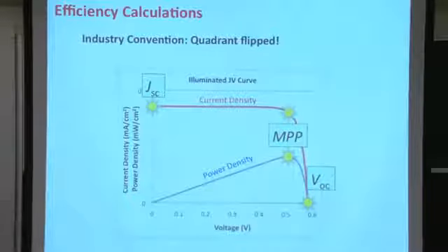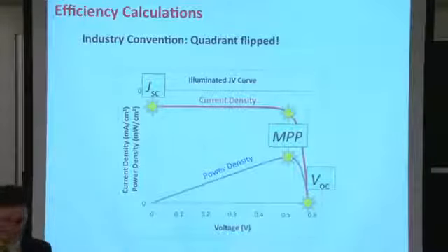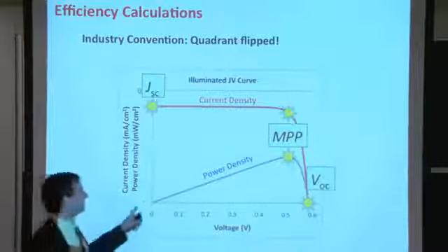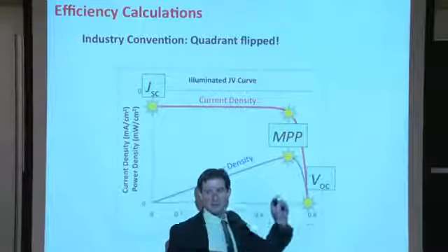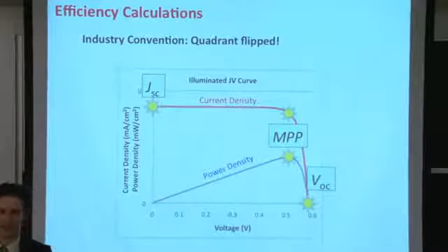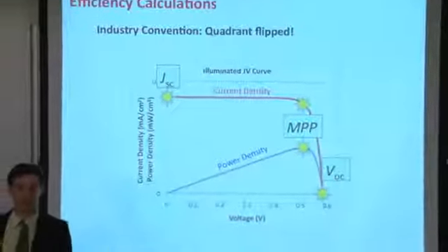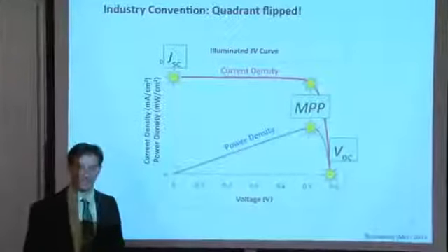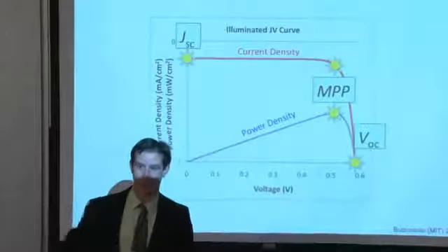To ensure that the device is working at the maximum power point, does an external voltage have to be applied to it? So to ensure that the solar cell device is operating right here, a couple of things need to happen. You need to have the right illumination conditions, and you need to have the right load. So the two need to be matched to each other. Absolutely. And that's where some of the power electronics come into play.